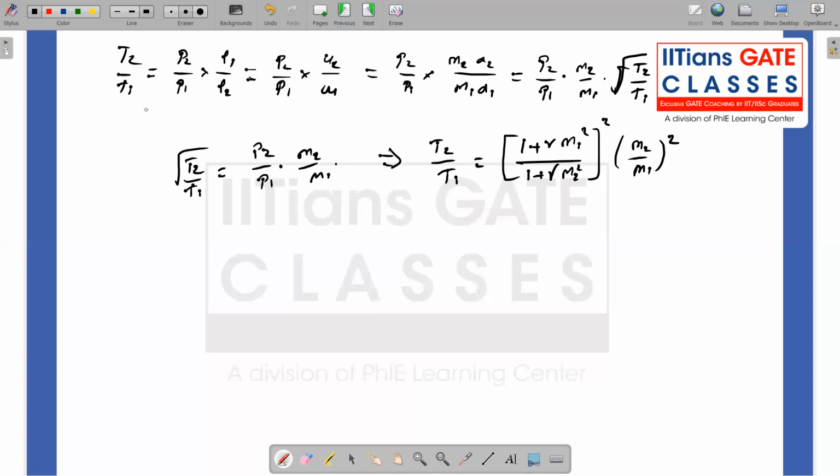And if I want to calculate rho 2 by rho 1, again the same process. Rho 2 by rho 1 can be written using P is equal to rho RT. So I can easily write it in terms of P2 by P1 times T1 by T2. So use the definition of P2 by P1 and T2 by T1. That should give you 1 plus gamma M1 square divided by 1 plus gamma M2 square times the inverse of T2 by T1.